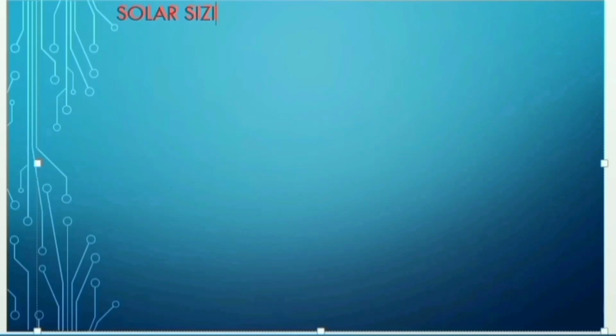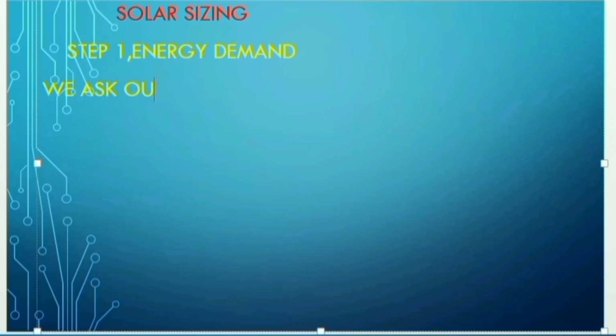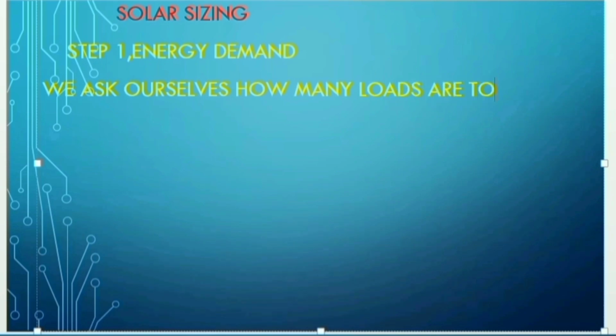Hello guys, today I'm going to introduce you to solar sizing. Our step 1, we look for energy demand. To look for energy demand, we ask ourselves how many loads are to be connected to our solar system and for how many hours in a day.